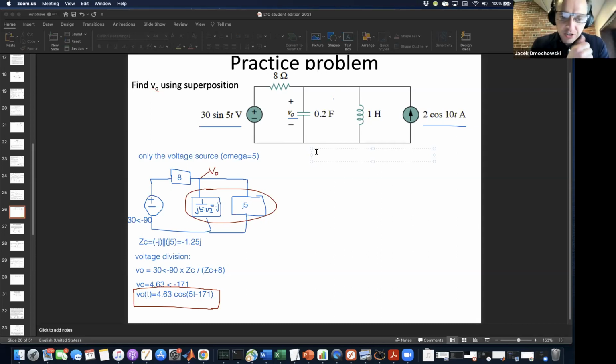Yeah. So if you had a battery and you had impedance 1 and impedance 2, and this is V and this is R1 and this is R2, then voltage division just means that the voltage across this resistor is equal to R2 over R2 plus R1 times V. And you're doing the exact same thing here, except that you've combined these two, which are in parallel.